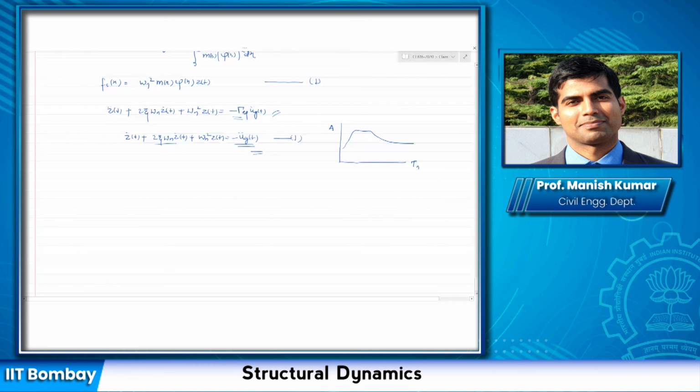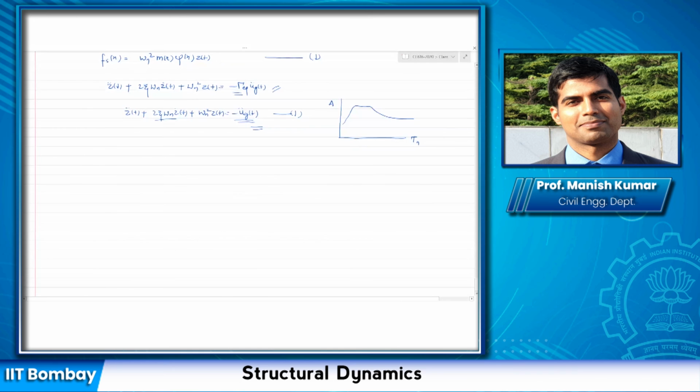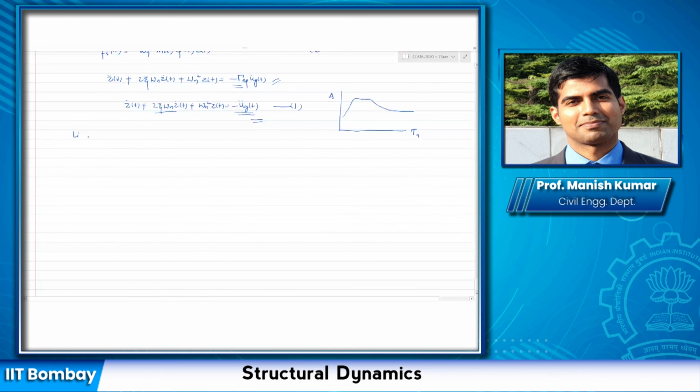The peak pseudo acceleration is A, peak deformation is D and V. For this system, it would be nothing but the same quantities multiplied with this factor because it is a linear system. And this is some of the problems that you have done, isn't it? That response spectra is scaled to a peak ground acceleration of 0.25 g. Whatever the PGA is, you basically scale it to 0.25 g. So it is something similar to that.